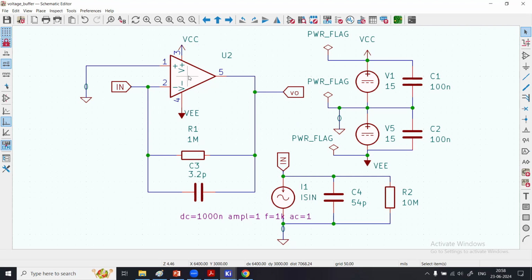Search with this phrase, transimpedance amplifier plus photodiode for smoke detector. And then the manufacturer parts will be shown up. Use that part, use the spice model, map the symbol pins with the model pins correctly. We have shown in our previous model how to do that precisely. And with all that reference, simulate your results and put your answers in the comment sections, right?